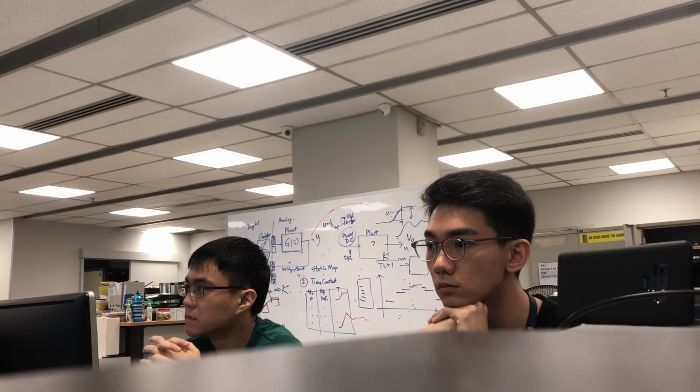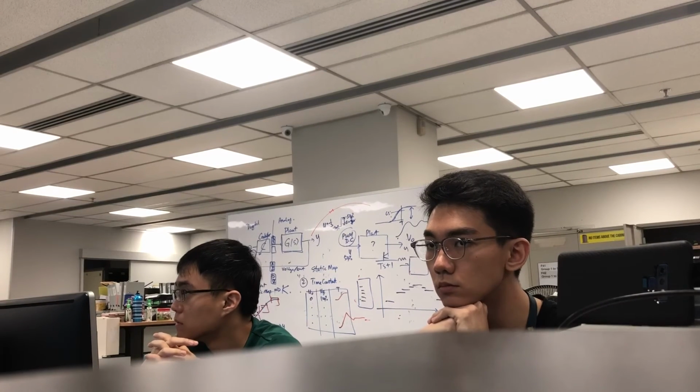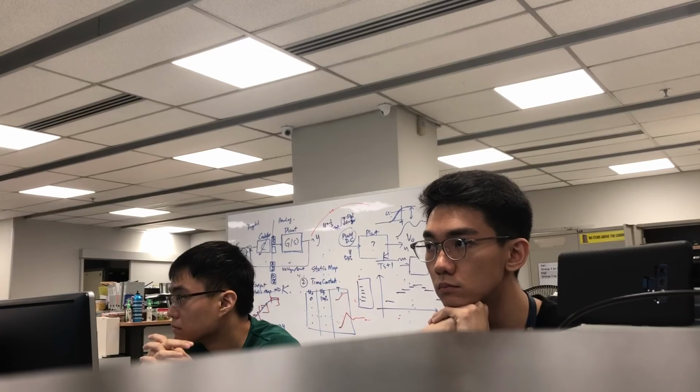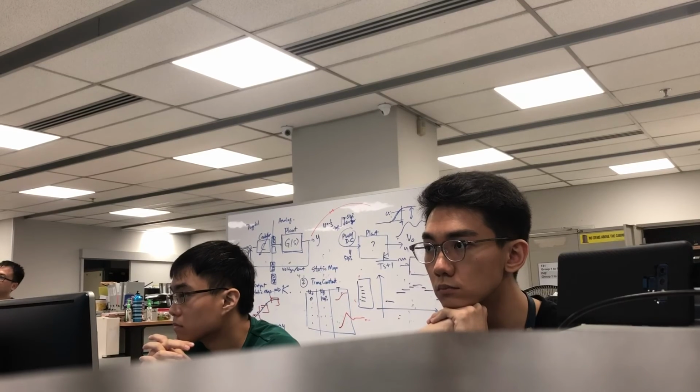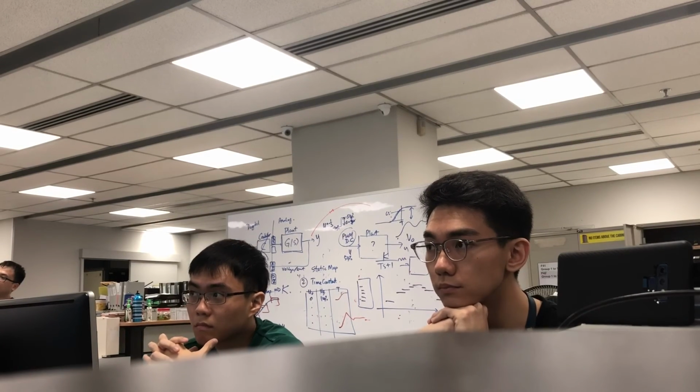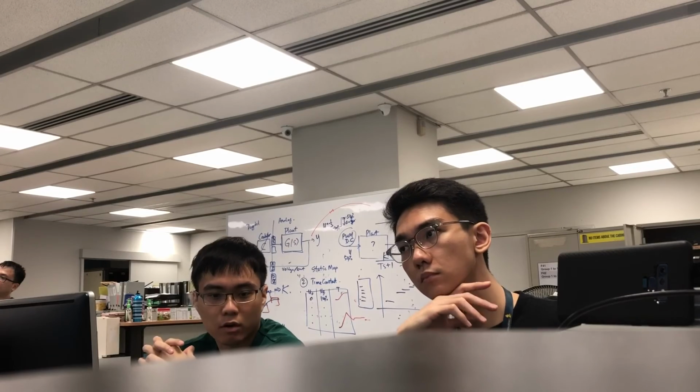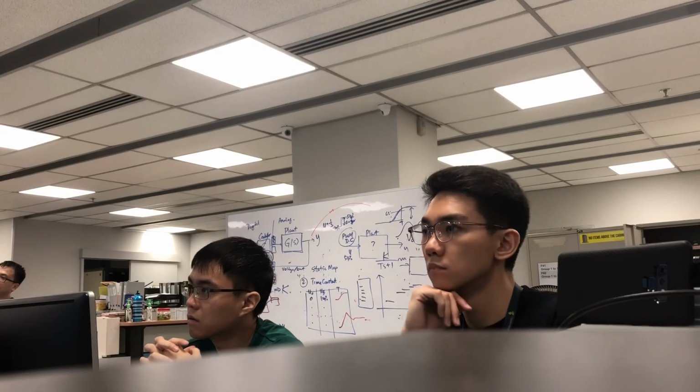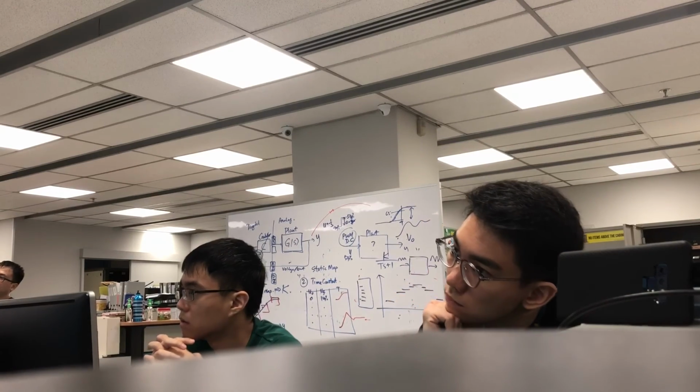Okay, so if you imagine there's a microcontroller, you will connect the output to the ADC input. You will connect the PWM pin to here. Okay? Alright, now very important. The ADC input can only take 0 to 5 volts. Means what? Your DC-DC converter, in the ideal case, actually goes from 0 to VCC. Your VCC is 10 volts.